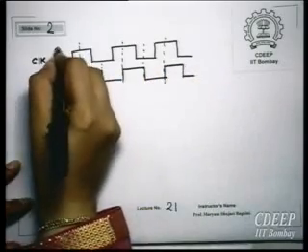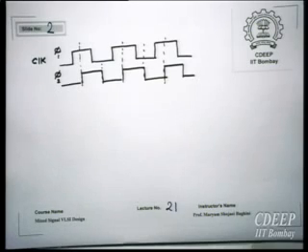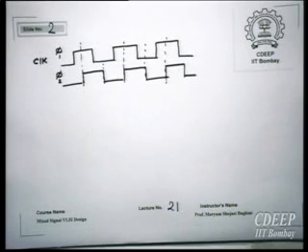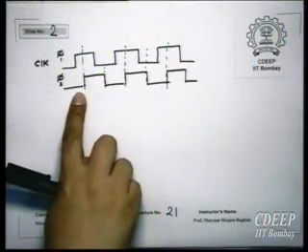So this is phase 1, this is phase 2. One way of generating these different phases, which are very much used in digital applications, is, for example, suppose you put 2 PLLs in such a way that the steady state phase error is not 0. So the PLL has been designed to have some steady state phase. Therefore, it is type 1, right? Now in this system you have 2 PLLs, so you can design the PLL in such a way that it gives this phase shift of, for example, pi upon 2.